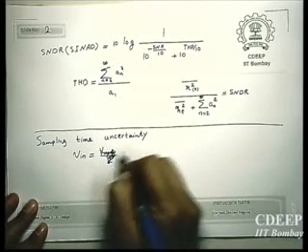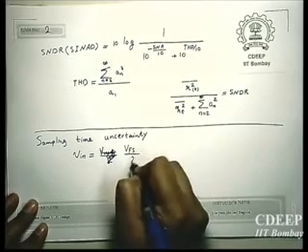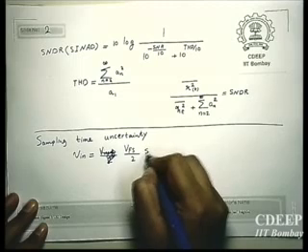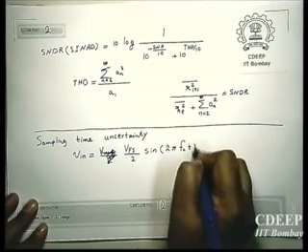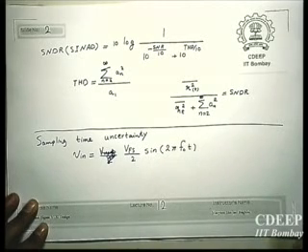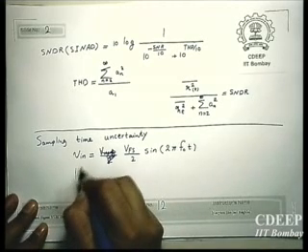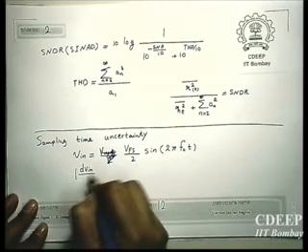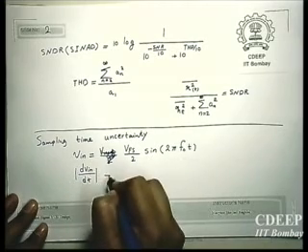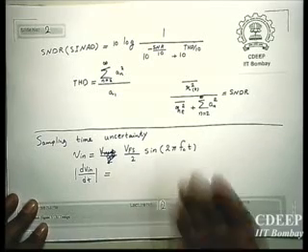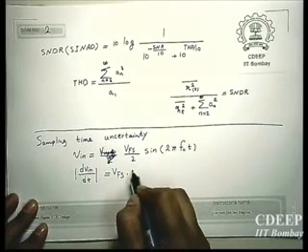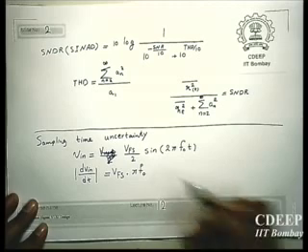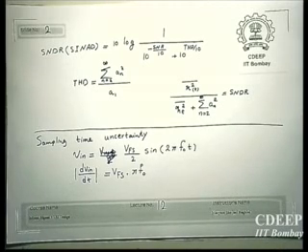Let's make it full scale, since everywhere we talk about full scale. It has a frequency F0, and you want to sample it. How fast does this signal change? The maximum rate of change is at the crossover points, which is V full scale times pi F0, right? This is the maximum change in the signal.